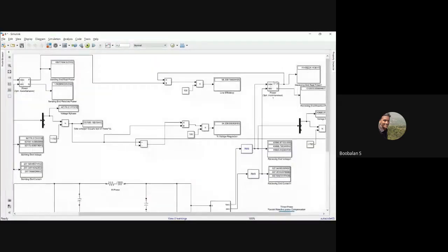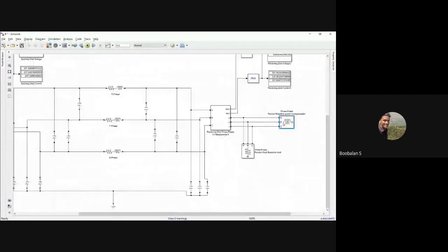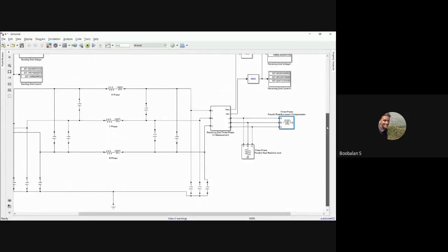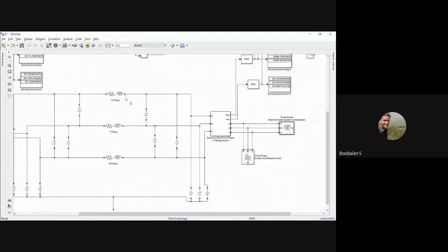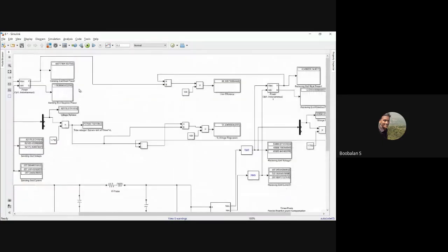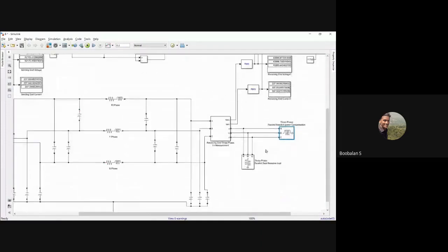Now I just increased this, right? So I increase my reactive power in such a way that I can remove my ferranti effect, so that you're going to have somewhat real values over here. If it is real transmission line parameters, we just choose these values, that's called the design aspect. If we have real transmission line values, no issue, it will be a perfect curve, because actually we are just choosing assumed values by trial. That's why it will be somewhat changing. Now it will be okay, because I'm increasing my reactive power, in such a way that you are going to remove my ferranti effect.